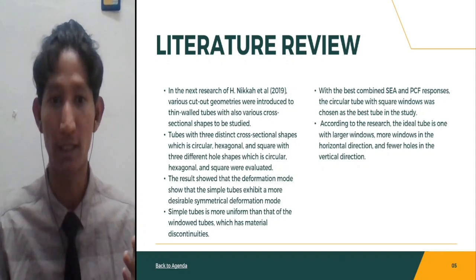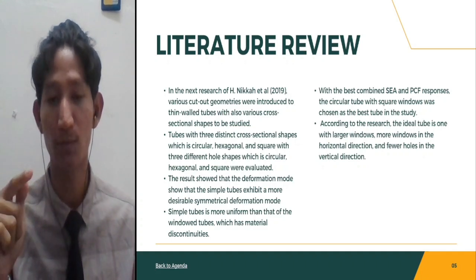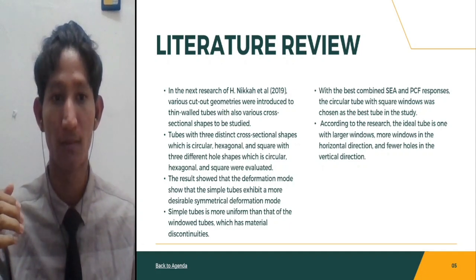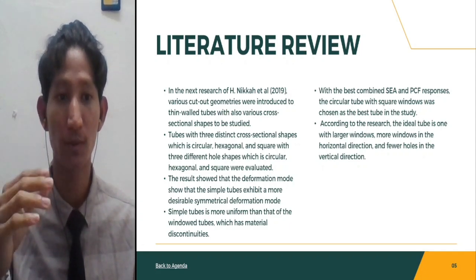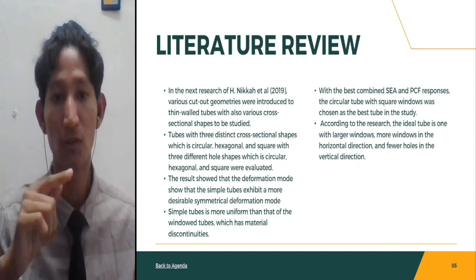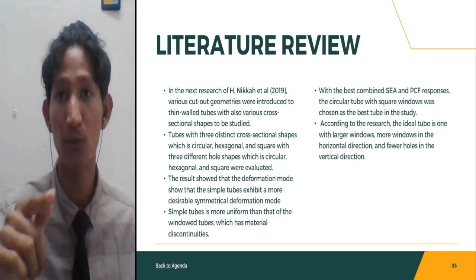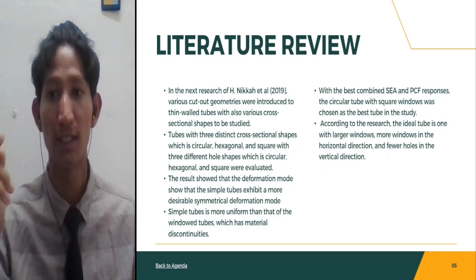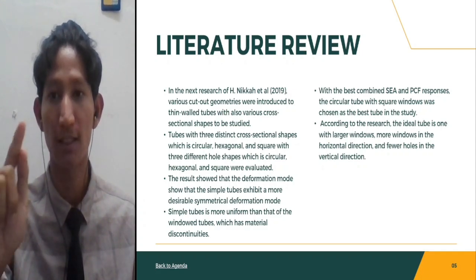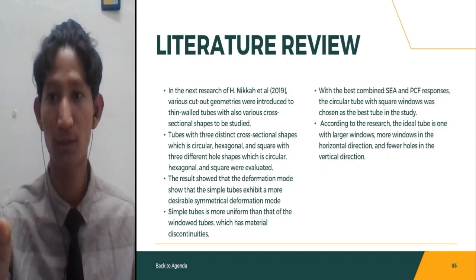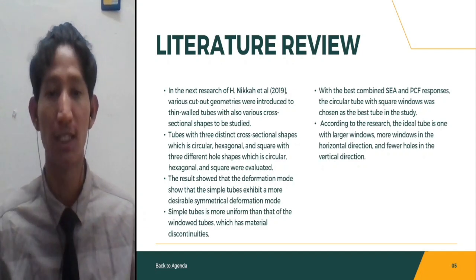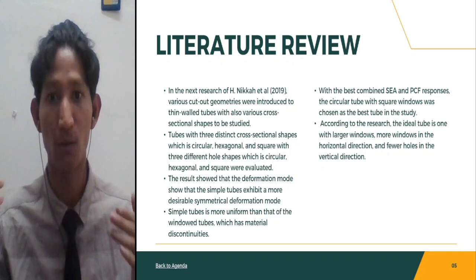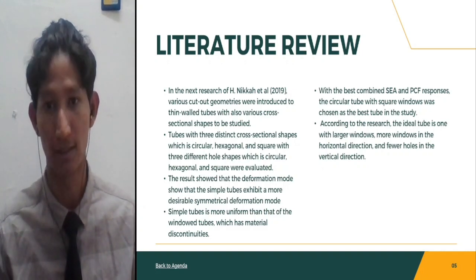The results show that the deformation of simple tubes is more symmetrical than window tubes, as window tubes have material discontinuities and simple tubes are more uniform. With the best combination of specific energy absorption, SEA, and peak crush force, PCF, response, the circular tube with square windows at the side wall of the tube was chosen as the best tube in the study.